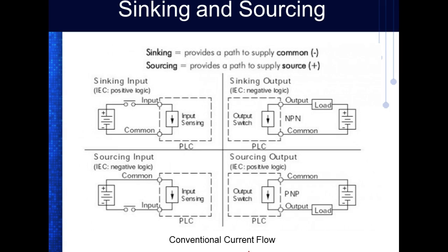And, of course, this doesn't come into play in AC. I was looking at this little Series 1 PLC up here, and it uses AC inputs and AC outputs. The AC has no polarity, right? You understand that? Because it changes so fast. But when I start dealing with these DC modules, then we're either going to have sourcing, or we're going to have sinking, or we're going to have what we configure. Now, most of them now are configurable. And I'll show you how to do it. So most of them, but you do it in groups.